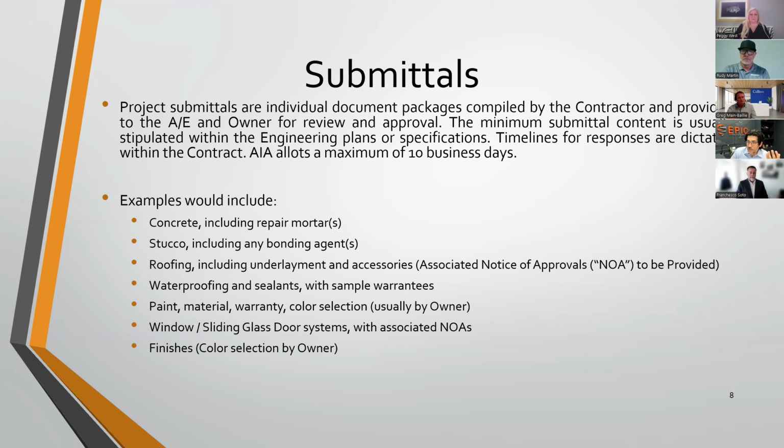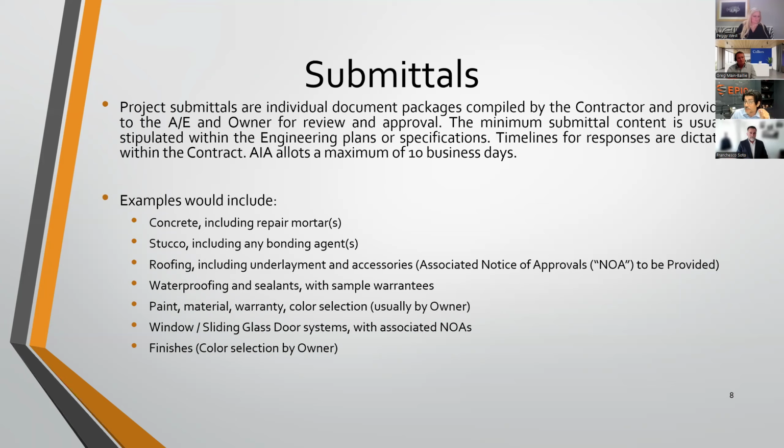Because in my plans, for example, if I am going to specify a specific waterproofing, I picked that for a reason. It's going to be Tremco something or other, or Sika something or other, at a certain thickness, but you may see the term "or approved equal." And that approved equal item needs to perform at the same level.